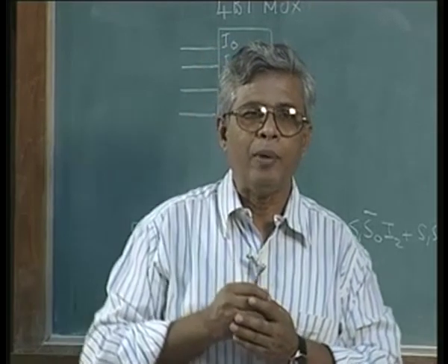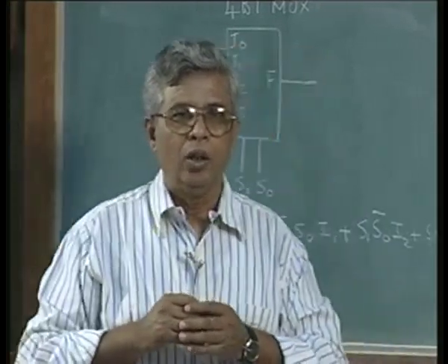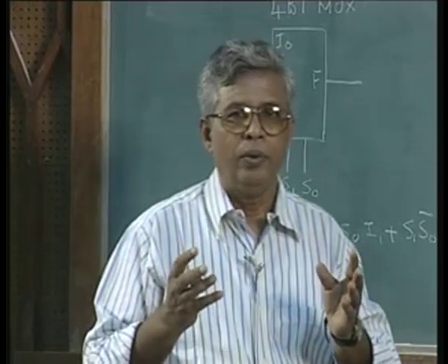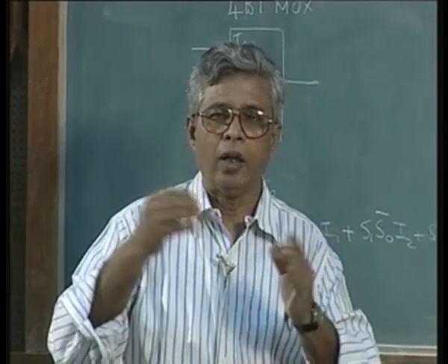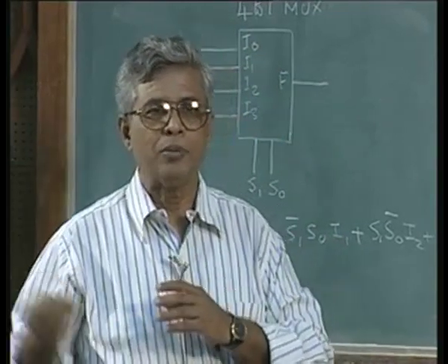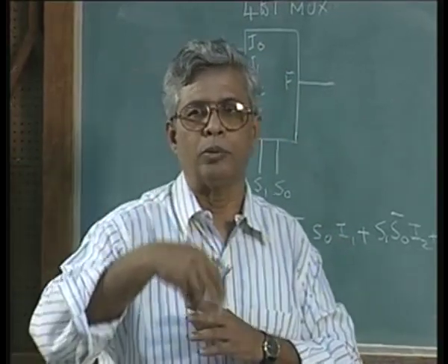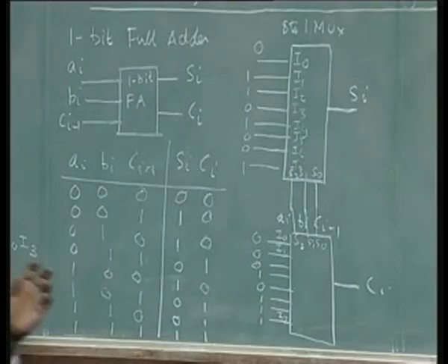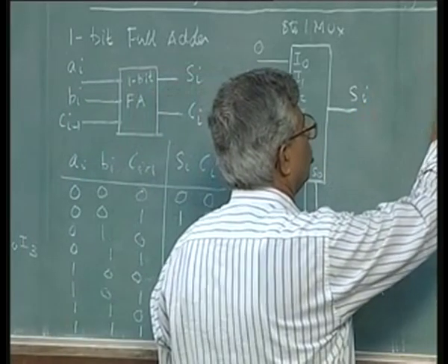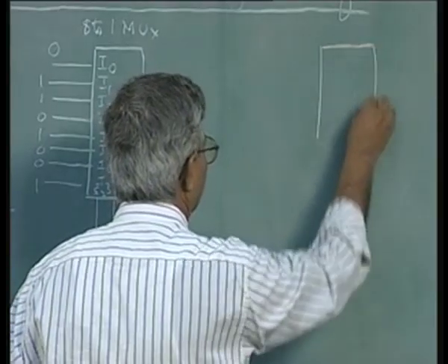Like in the Karnaugh map case, if you are given a free ride, you would use AND gates, OR gates, inverters. But if the person says use only NAND gates, we will do some further manipulation. The same concept here, I am going to use 2 4-to-1 multiplexers.